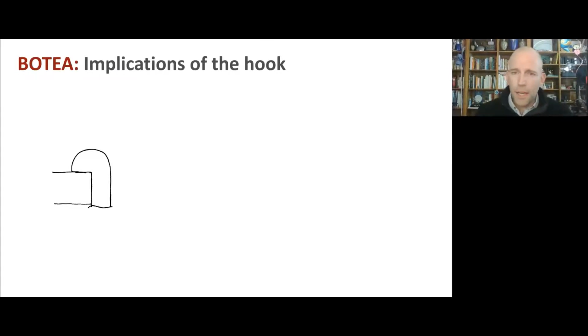Just from this, we can understand some implications for what this section of material will experience. So if we draw a free body diagram of it, we've got that reaction force in the vertical direction. And as we saw just a minute ago, that reaction force is going to be big. That's going to be something like twice the magnitude of the rope force, or bigger if that left-hand side lever arm is smaller.